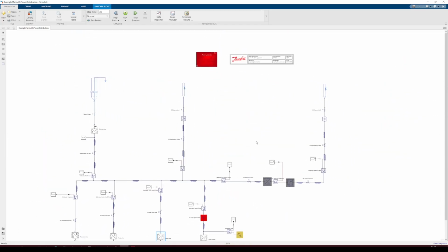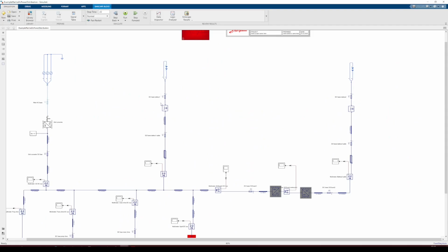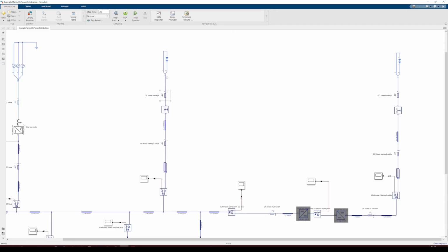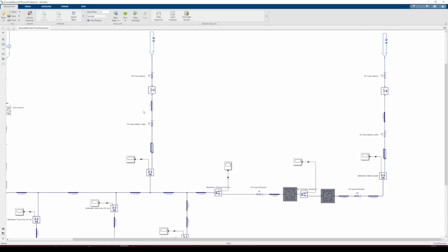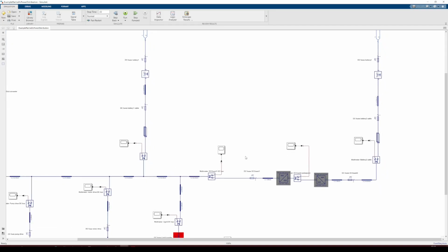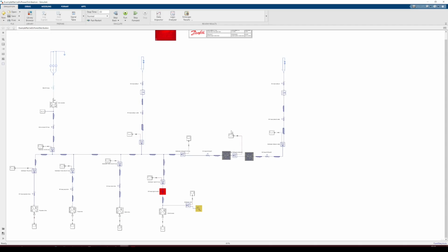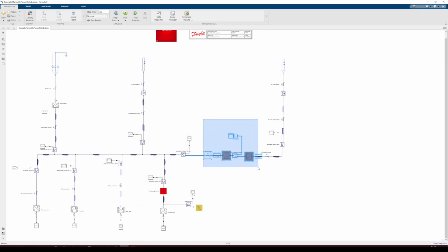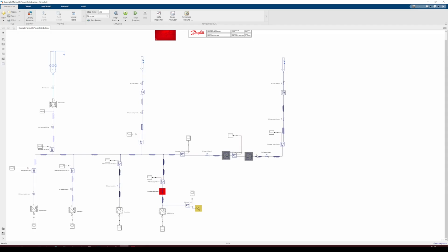What is more, we have two sets of batteries here. On the left hand side, the battery of this half of the system is here. So the battery has its own DC fuses, there's a DC switch, and then the cabling connection which ties the battery into the main DC distribution system here at this node. Here in the right hand side, we have the DC card, which separates the left and right hand sides of the system from each other in case of faults.